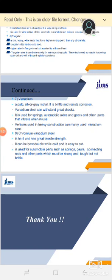Next is the combination of chromium and vanadium steel. It is hard and has great tensile strength. It can be bent double while cold and it is easy to cut. It is used for automobile parts such as springs, gears, connecting rods and other parts which must be strong and tough but not brittle. Okay, that's all for today.